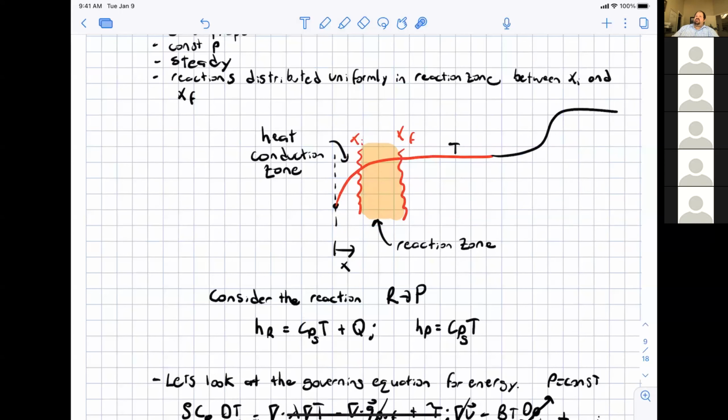Yeah, it's sort of confusing, but you sort of need to view this as, in general, the gas phase flame structure, even for a homogeneous propellant, is sort of a double flame. There'd be a flame following another flame. The first flame would be the chemical reaction in the fizz layer, and the second flame would be the exothermic reaction of the dark zone species. Okay.